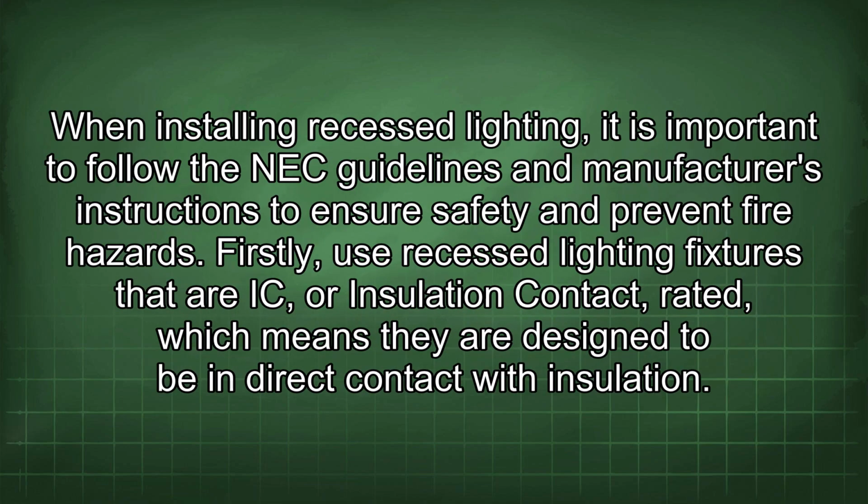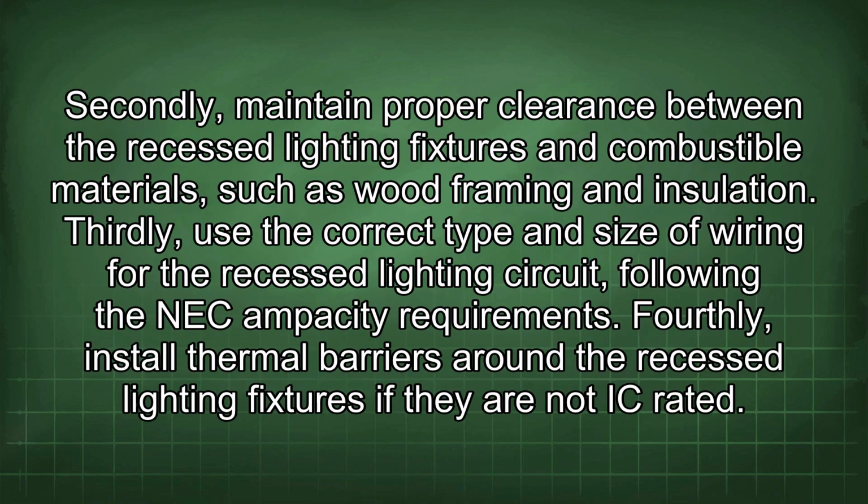When installing recessed lighting, it is important to follow the NEC guidelines and manufacturer's instructions to ensure safety and prevent fire hazards. Firstly, use recessed lighting fixtures that are IC or insulation contact rated, which means they are designed to be in direct contact with insulation. Secondly, maintain proper clearance between the recessed lighting fixtures and combustible materials such as wood framing and insulation.